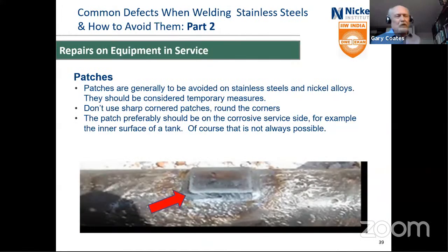Patches, that's what often people think of, whether it's a pipe or a tank. Generally, we tell people to avoid doing them because, again, you put on a patch and somebody thinks, oh, well, I can just run it for the next 10 years with the patch on. And patches really are only a temporary measure. You have crevices underneath the patch. If you do use a patch, ideally you put it on the corrosive service side, but that is rarely possible.